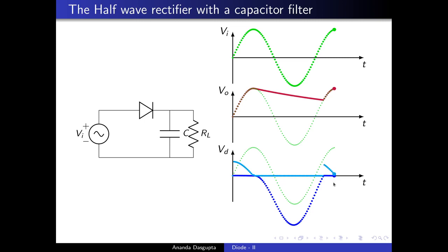There is a current which again falls to 0. And then you have 0 diode current and a reverse biased diode as the input voltage again drops below the peak. So this behavior, a sudden spike in the diode current which then decreases to 0 once the input voltage reaches a peak, is going to keep on repeating over and over again.